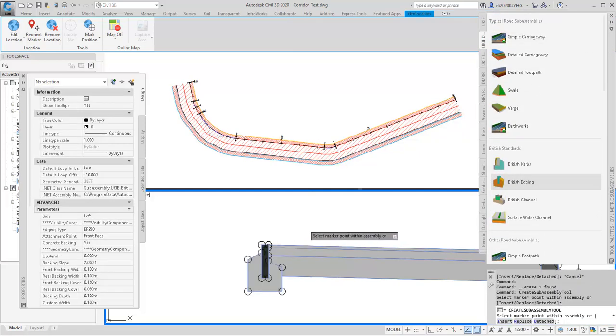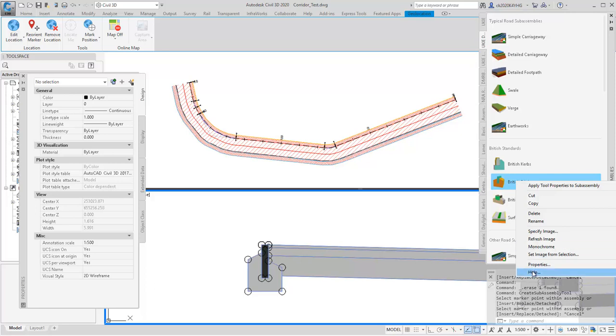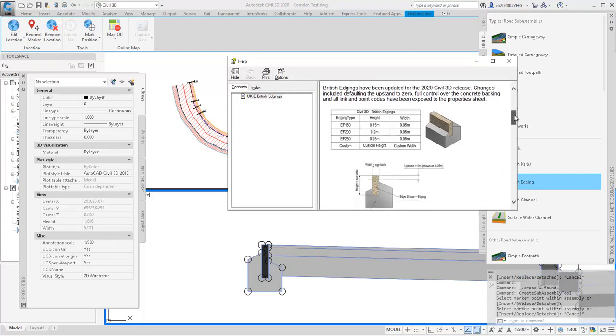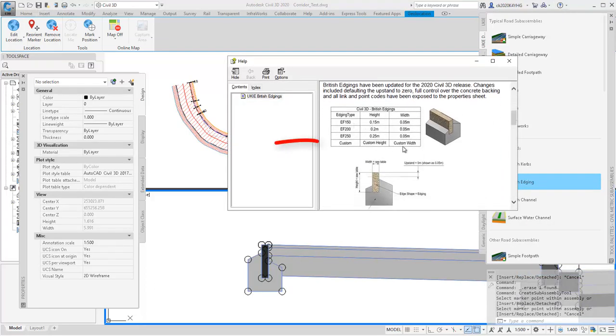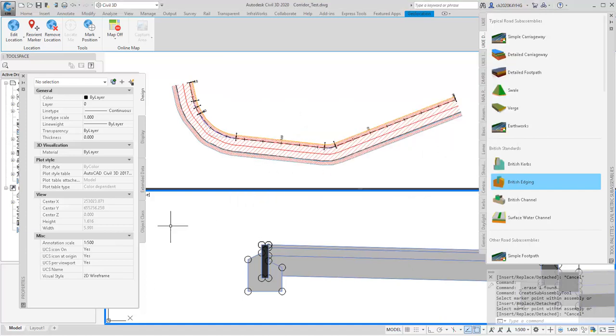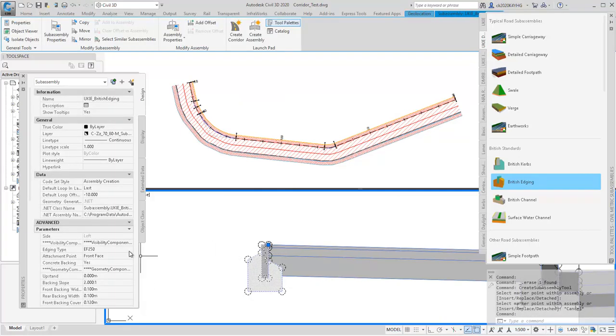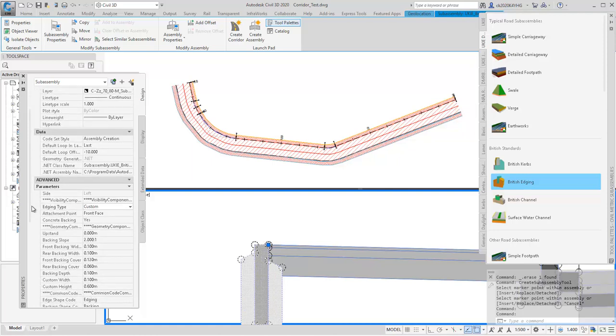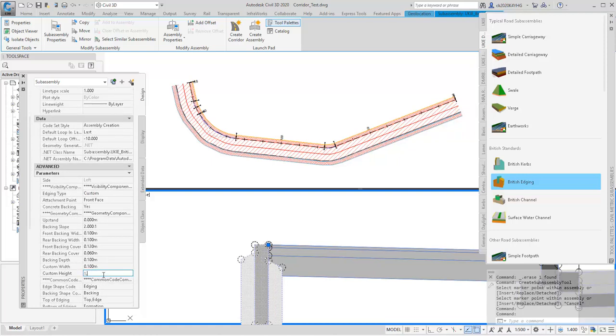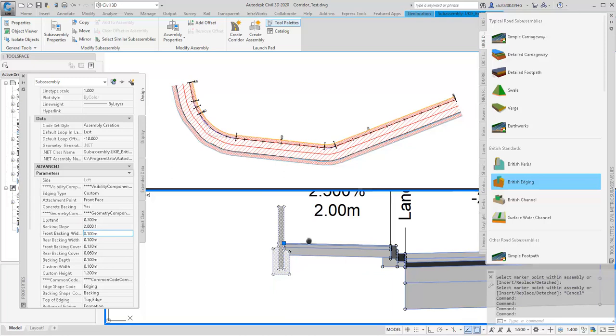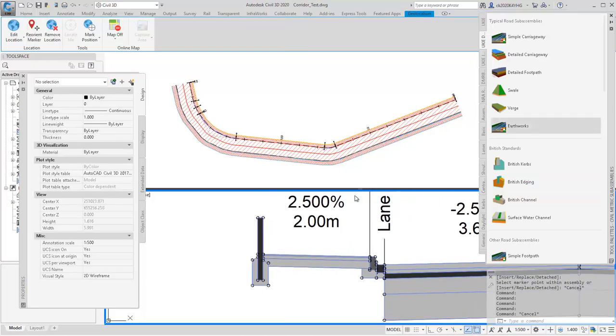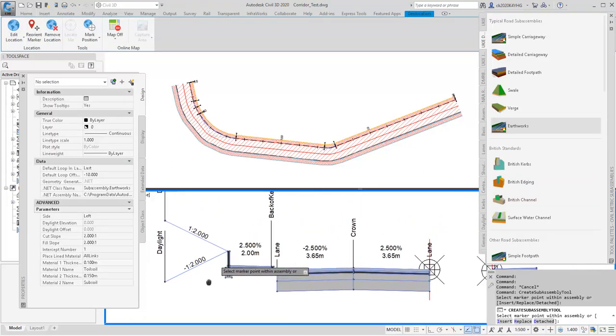And look at the documentation again. Notice the availability of a custom option as well as the standard designations. This means you can overwrite the default values to anything by choosing custom and altering the custom parameters. You know what it's like. You often find a subassembly that's so near to what you need, but then it's limited by design, and that can be very frustrating. Maybe you're a landscape designer who just wants to put a quick vertically mounted flagstone on his corridor to show a planting area.